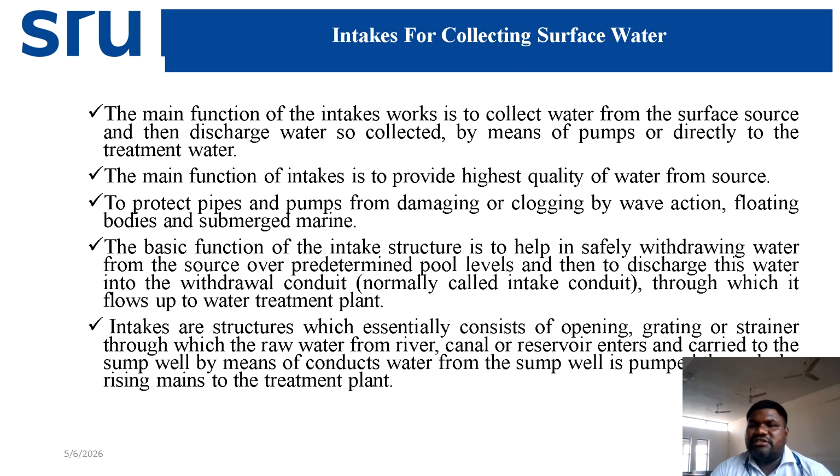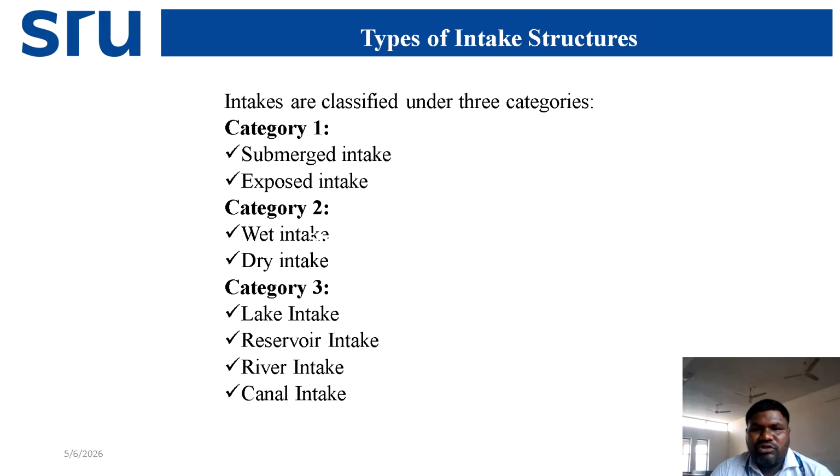So what are the intakes for the collecting of surface water? The main function of the intake works is to collect water from the surface source and then discharge the water so collected by means of pumps or directly to the treatment unit. The main function of intakes is to provide the highest quality of water from the source. I will show you the different types of intake structures.